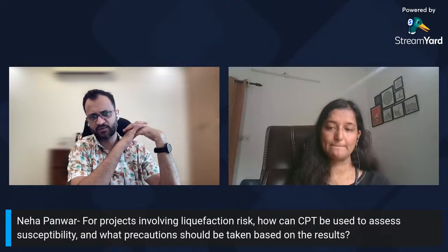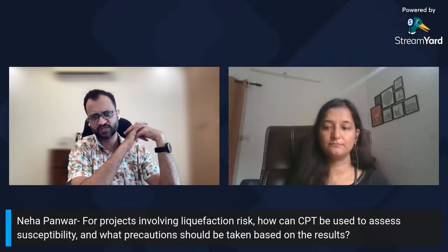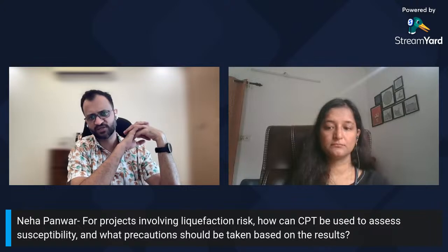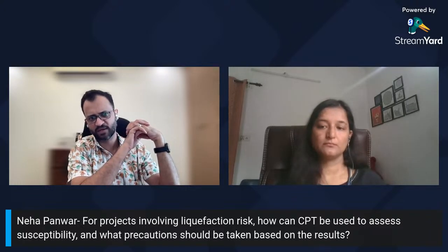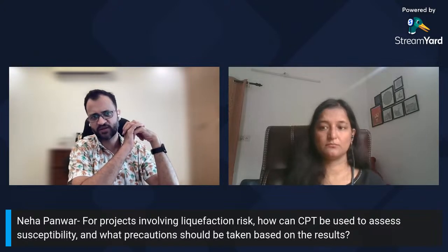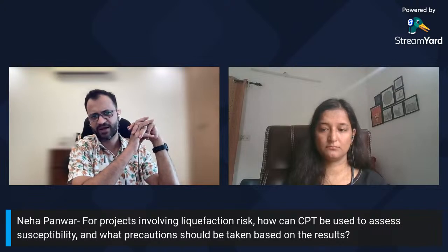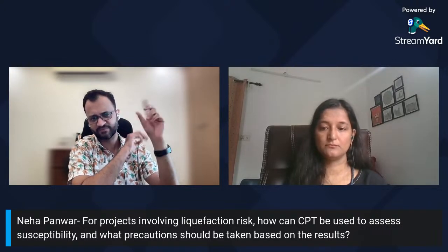Neha, for projects involving liquefaction risk, I'm actually a huge fan of doing CPTs because, as I mentioned earlier, and if you look at international literature as well, CPT is the preferred method for getting your CRR profile or your factor of safety against liquefaction profile. Along with that, I would always like to do shear wave velocity profiling and possibly a few SPTs with SPT energy ratio correction.